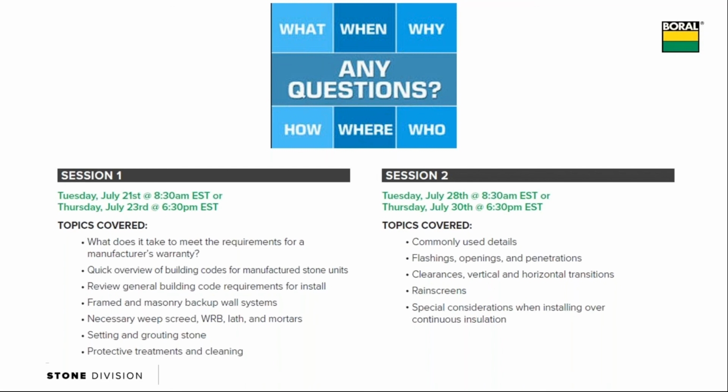So if you accidentally bump the stone, you could fix it without pulling it off. Or if you decide, hey, I need to move this stone over a 1/2 inch or a 1/4 inch to make it fit a little bit better, you can do that too. So another reason to consider using a modified mortar above just the additional bond strength that you get with it.